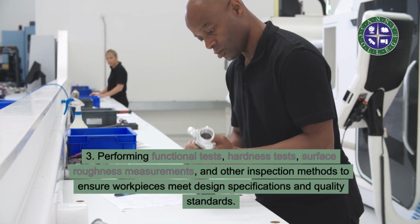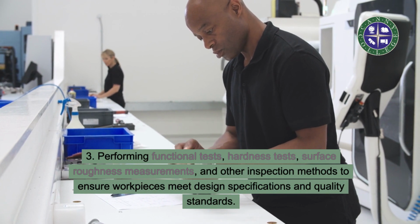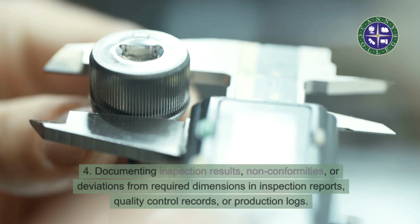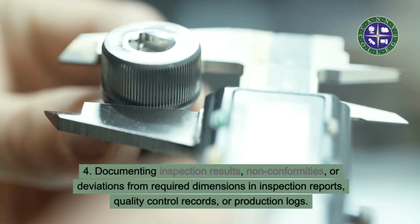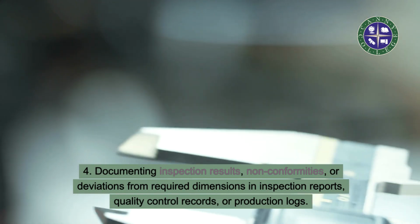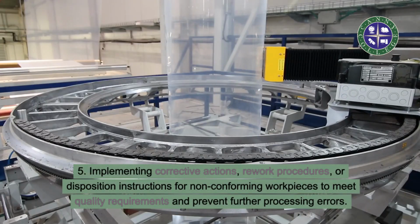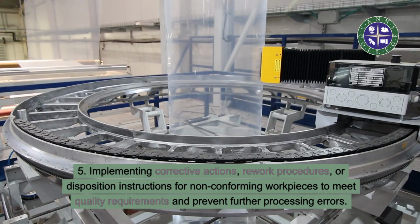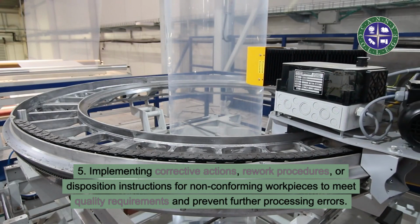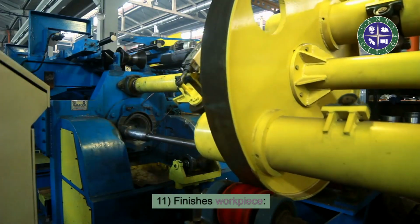Performing functional tests, hardness tests, surface roughness measurements, and other inspection methods to ensure workpieces meet design specifications and quality standards. 4. Documenting inspection results, non-conformities, or deviations from required dimensions in inspection reports, quality control records, or production logs. 5. Implementing corrective actions, rework procedures, or disposition instructions for non-conforming workpieces to meet quality requirements and prevent further processing errors. 11. Finishes workpiece.